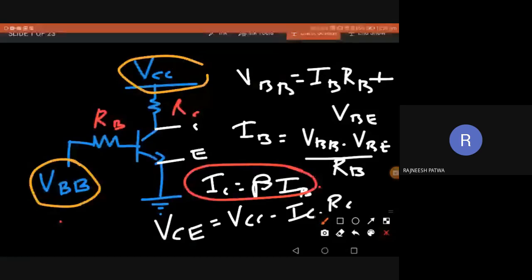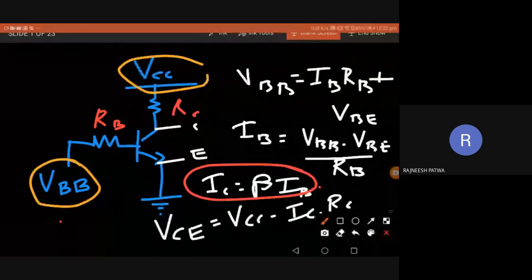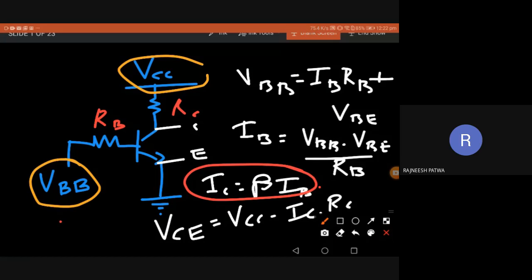That is okay. But this type of circuit is mainly used in digital switching, where I have an input of 1 and 0. You remember we have switches like AND gate, OR gate, NOT gate, etc. If I give a high at the base, your output will be 0. If you give 0 at the base, the output will be high. This kind of digital switching can be applied.